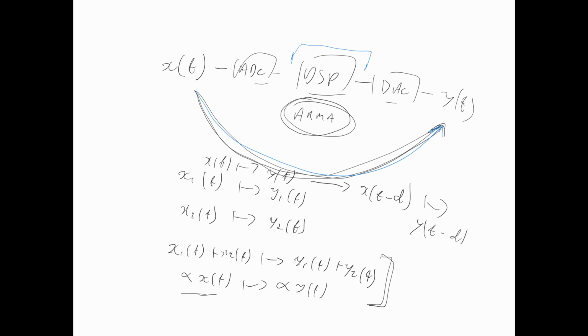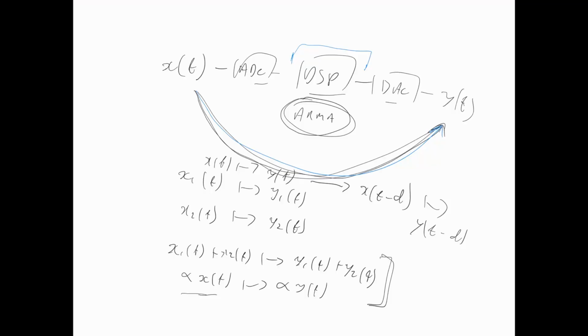The fact that the system is also time invariant really helps with this. We can take a simple signal and we can delay it or push it forwards into the future, and again we know exactly how the system is going to respond. So what we will see is that there are two very nice properties of LTI systems. If we put a sinusoid into an LTI system, we get out a sinusoid of the same frequency. This is what we mean by applying a simple signal, a signal that it's easy for us to understand what the output's going to be.